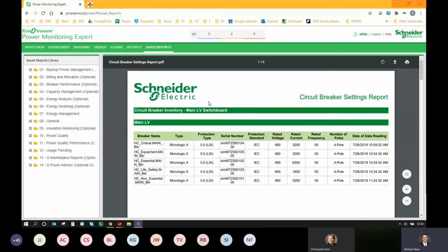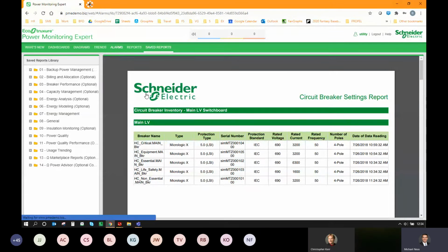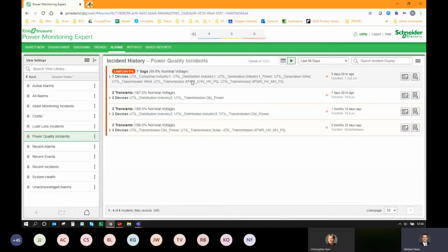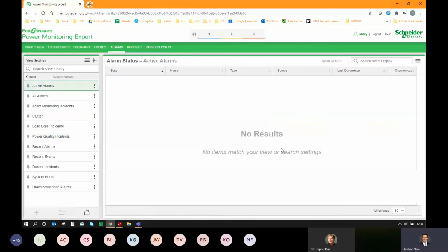But we can certainly monitor your individual phase voltages for dropouts, and you can set the individual limits to be wherever you want to alarm on that. That's one of the default alarms in there, things like phase open. So that should automatically report back here. That would show up if you clicked on active alarms and you had an open phase. You should see that in here. Okay.